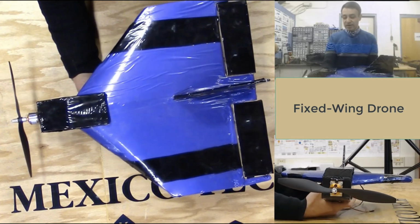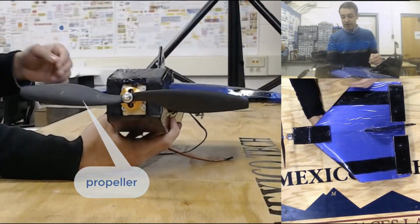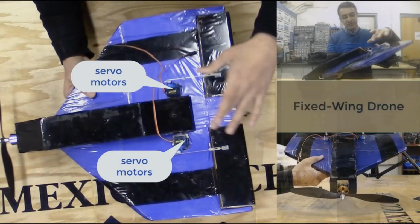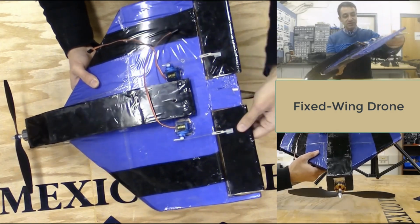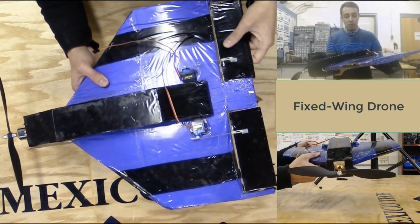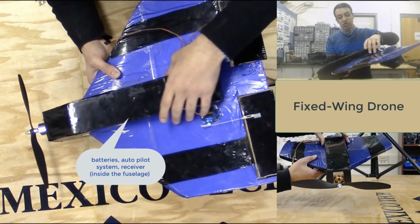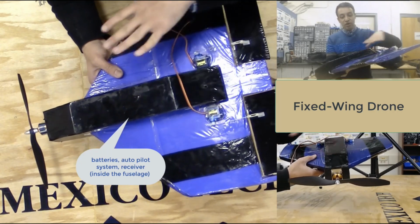For the electronic part, we have a brushless electric motor, and a propeller that acts to generate the thrust for the forward flight. We also have two servo motors that act as the actuators for these control surfaces, so they can change the angle in order to take off or land, or for loitering flight. The rest of the equipment, including the batteries, autopilot system and receiver, all go inside the fuselage. So the shape and the size of all these components is very important to fit all the electronic equipment inside the drone.